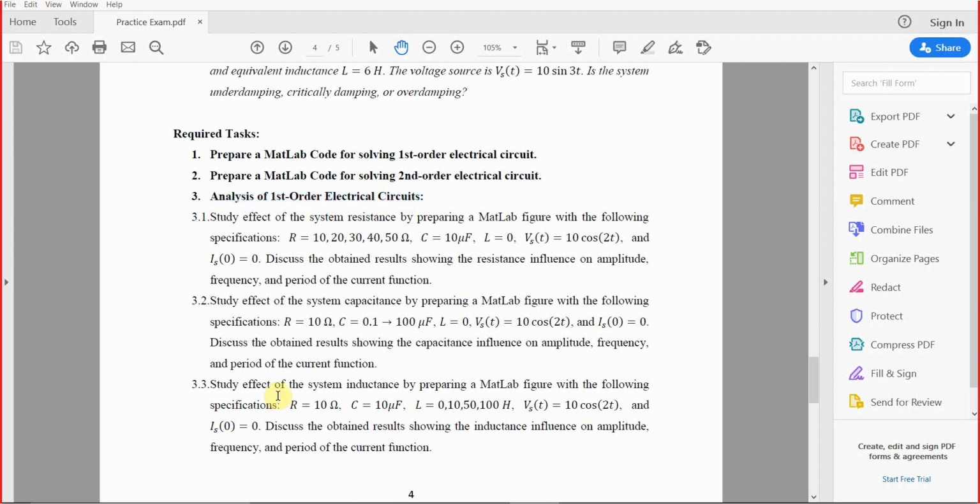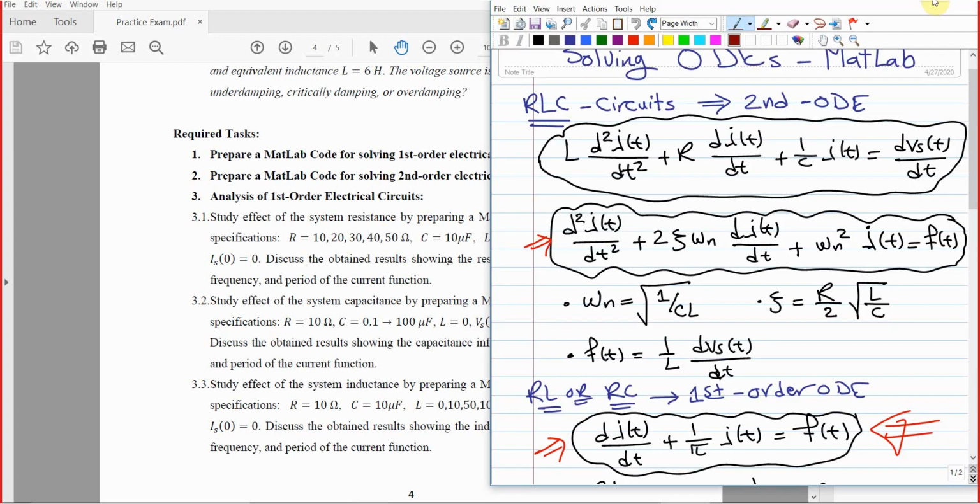So for example, you're going to use the first order ODE MATLAB code to study the effect of the system resistance, which is R. If we change R, if we increase R from 10 ohms to 50 ohms, what's going to happen to the current? Is it going to increase or decrease? But the current is a function of time and it is a wave function. So what exactly is going to increase or decrease? Any wave, to be fully described...